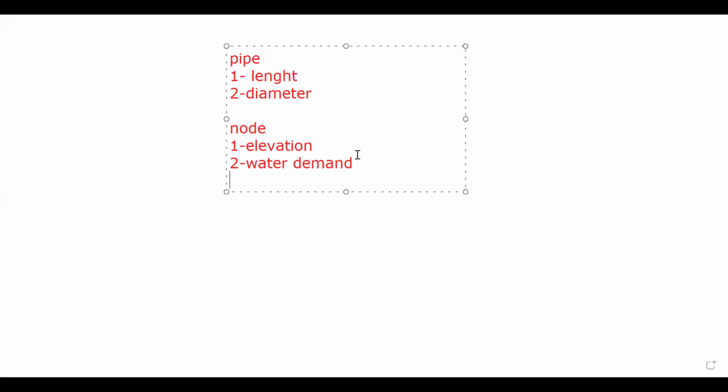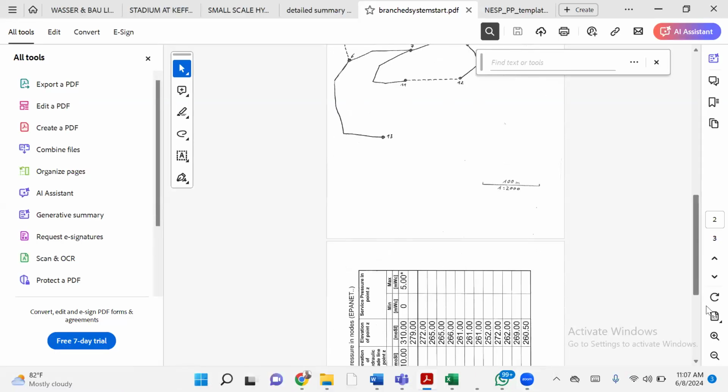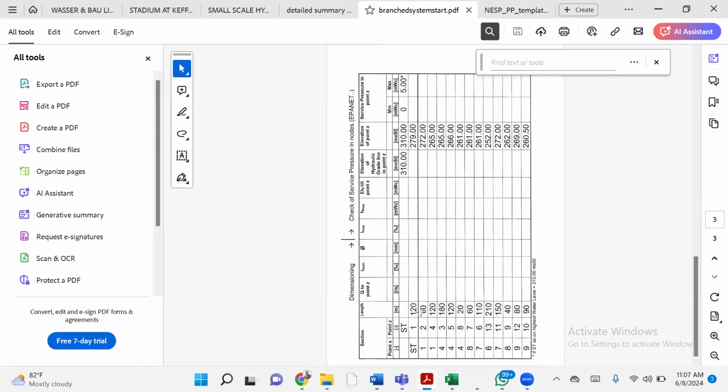I told us last week that out of these 4 parameters, if you send a surveyor to site, you already have 2. And those 2 you have are the length and the elevation. Every surveyor that goes to site and comes back will list out the length of each section. Those lengths of sections are what you put in Excel. As I indicated, you must put it in Excel and it will look this way. So those lengths that they call out from the surveyor, you put here.